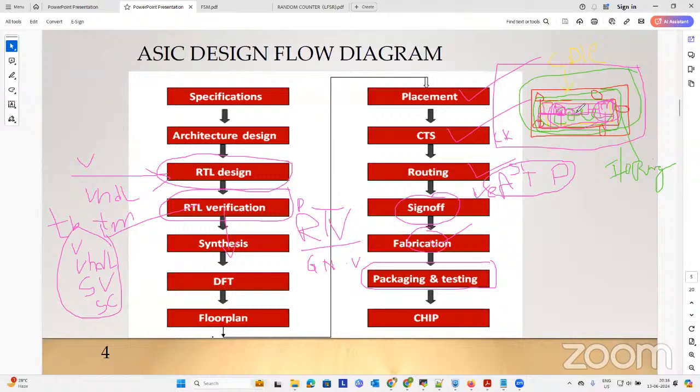ASIC design flow. So we are going to connect the clock nets. So we have sequential designs, we have macros, and all these designs has internally the clock pins. Either they are positive edge or negative edge. Routing the clock nets is called clock tree synthesis. That is CTS. Clock tree synthesis. CTS is nothing but clock tree synthesis. Clear? Sai Shankar.